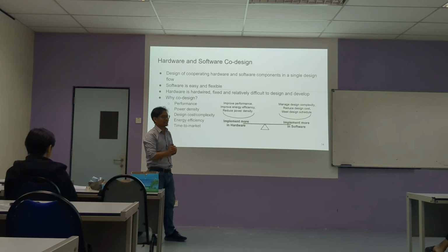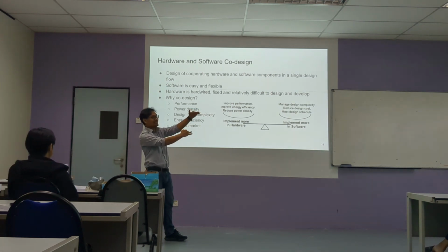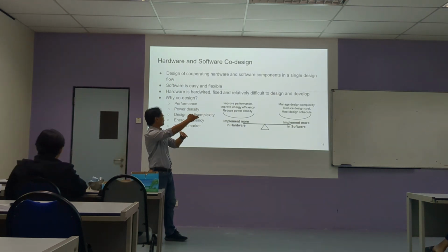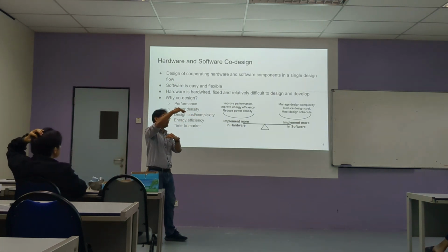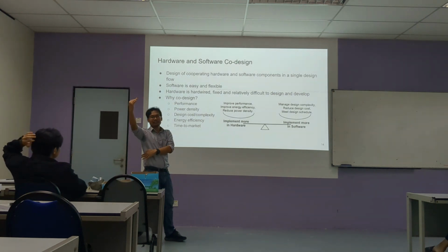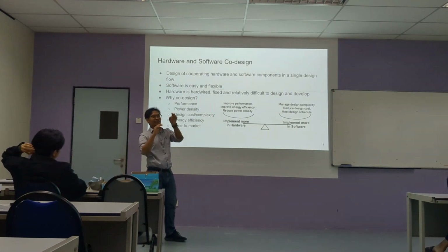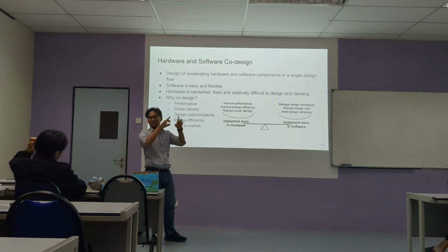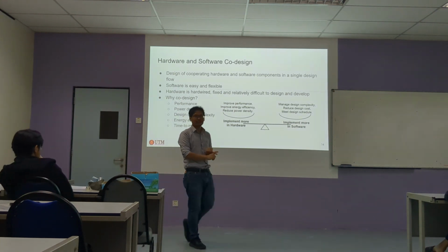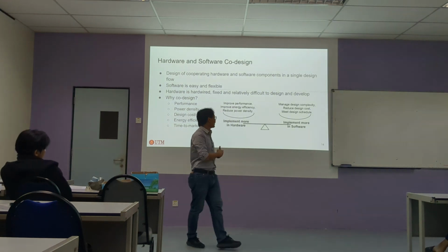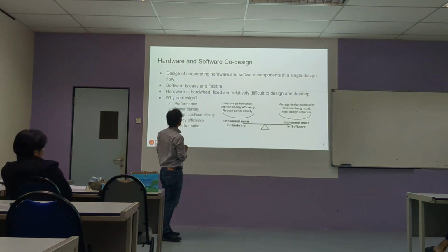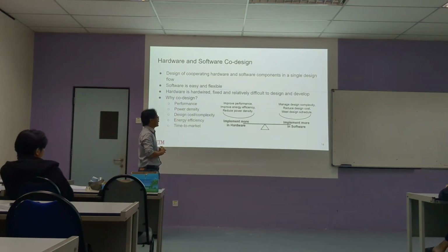Take the example of the sorting algorithm, right? If you have done a sorting algorithm in C or C++, it's very short, you can do it very easily, maybe 20 lines, 30 lines. But how many lines in the same algorithm, let's say bubble sort, in RTL? You have the CU, you have the DU, you have the top, you have to combine together, you have all the interconnections, you have the clock, you have the reset. So generally RTL hardware is more difficult to design, and it takes a longer time.